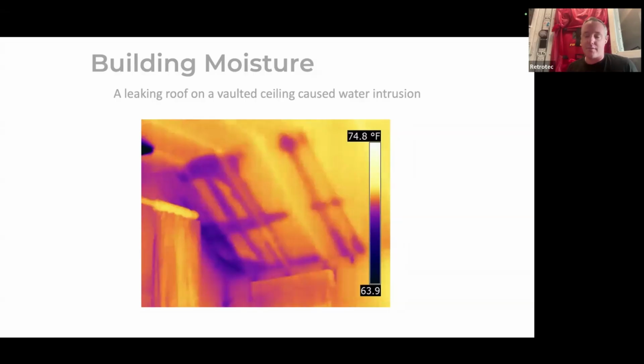So if those kinds of issues were going on, you would see that before you even turn the fan on. So you would know it's not really an air leak if it's that dramatic. I mean, sometimes you'll see some air leaks. You'll definitely see thermal bridging without a blower door running. So that's why it's really important to take those static images first. You might find an issue that's just not related to air leakage at all that you would interpret as air leakage if not. So it's important to understand, like, oh, I see a dark or a bright, white color. It's an air leak. That's not always what it means. It could be something else too.